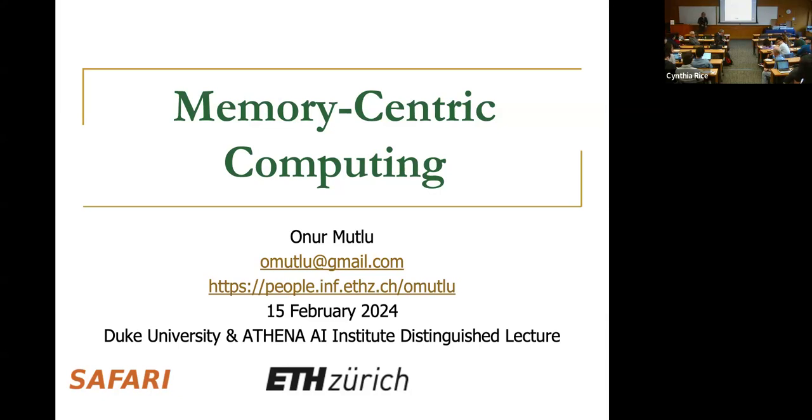Yeah, absolutely. So that's basically why we need these units to communicate from one bank to another. That's why I mentioned to Dan also, this is what I would like from DRAM manufacturers to implement. But there have been a lot of proposals to figure out how to move the data from one bank to another. RowClone has some of them, but later works also improved it. Certainly having support for moving data from one bank to another, and also moving to different parts of the row from one bank to another, is important. I mean, if we want to move the data from one bank to another bank, we also need an on-chip high communication bus or NOC or something.